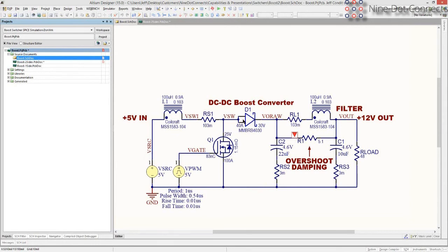What we're trying to do is make it so that the current that flows down through here continues flowing right there. If this diode and this switch are laying right on top of each other, then when this current stops, that current takes up, and they're ideally flowing in the same physical space down adjacent broadside tracks. So the net effect is the current continues to flow. To do that, it's necessary to find a common junction point where it switches from going down to going over. That's what we're trying to do: make the loop so that it doesn't create a problem.